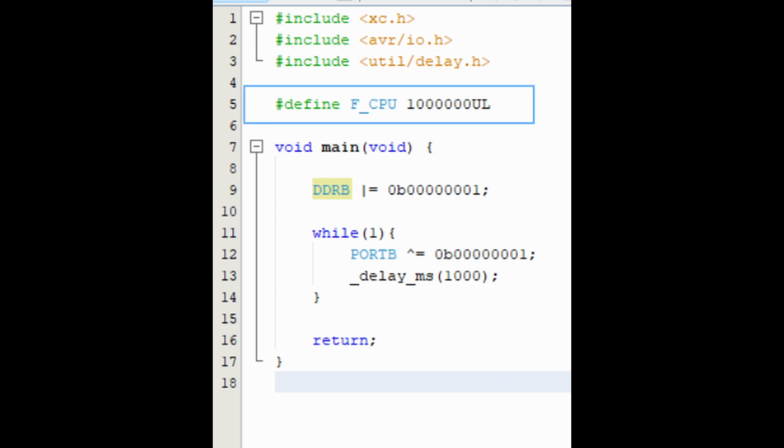To properly time the machine cycles, a constant clock is required for microcontrollers. This F_CPU macro defines the clock frequency which will be provided to the microcontroller with the help of crystal oscillators. Note that many microcontrollers have internal oscillators. Here for this example I am using the 1 MHz internal oscillator. To define the clock frequency, after writing F_CPU, write the exact frequency in Hertz which will be in use, followed by an uppercase UL. By doing that, you are telling your C compiler to treat 1 MHz as an unsigned long integer.